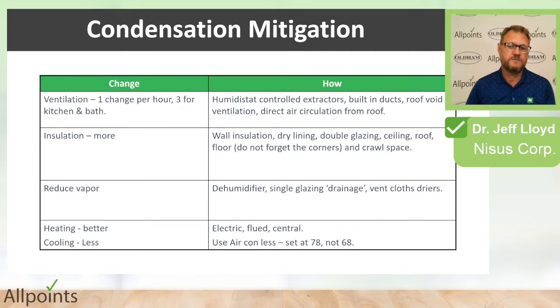A nice place to look for insulation and condensation issues is in bathrooms in the corners of walls, and I'll quite often see a black stripe in the corner of the wall, and the reason being it's one insulated wall meeting another insulated wall, but when the home was built, the corner where those 2x4s or 2x6s met wasn't insulated. It needs an extra bead of foam insulation there, and so you'll quite often get that black stripe.